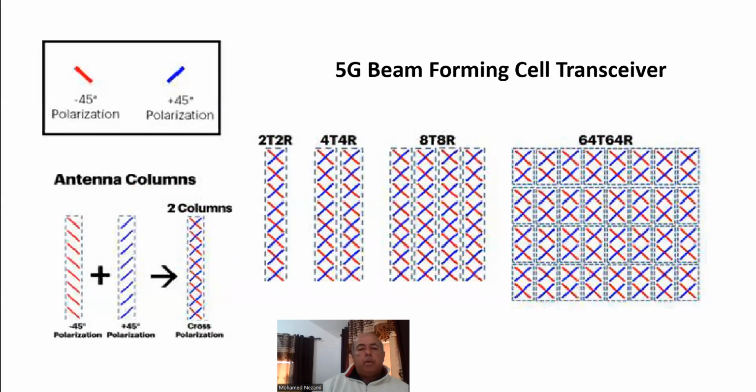The beamforming capabilities of the 5G millimeter wave start out at this point. Let's look at the antenna panel array for both the sub 6G and the millimeter wave. For these small cells and even macro cells, the antennas are done as follows. Usually these antennas transmit dual polarization. They don't transmit vertical and horizontal like SATCOM transceivers. Here, the polarization is rotated by 45 degrees, a slanted plus/minus 45 degree antenna. The two different colors correspond to the different polarizations, and it's almost like a standard.